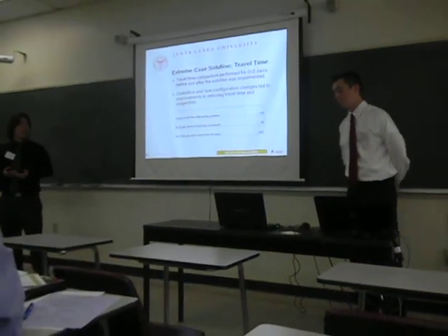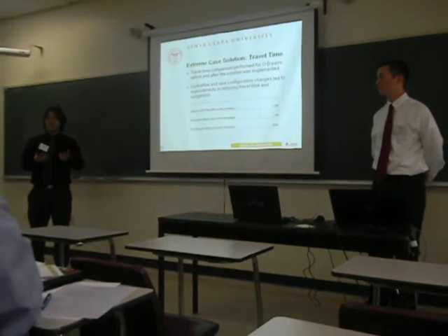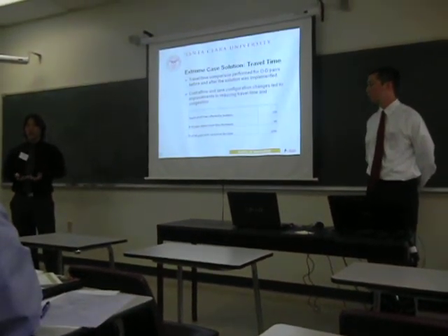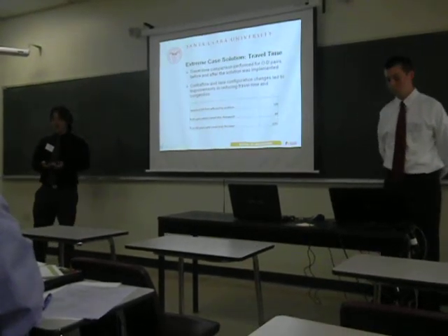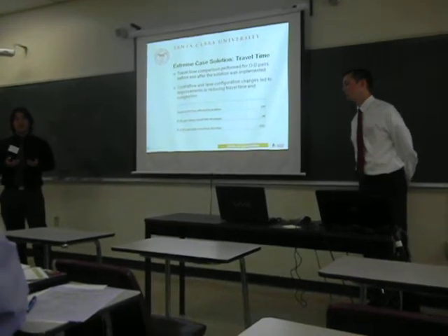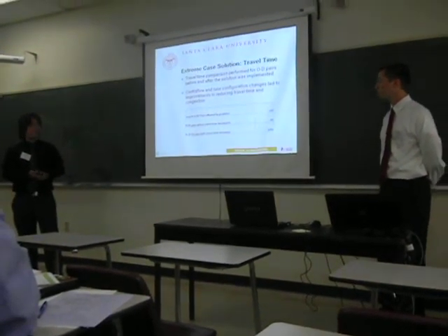We also did a travel time analysis for this, and of the affected OD pairs, we saw 63% of them saw a decrease in travel time after the implementation of our lane configuration. Why this number is not higher is because this is still an evacuation type scenario. So you cannot expect even a solution like contraflow to reduce all the traffic down to what it is in the base condition.